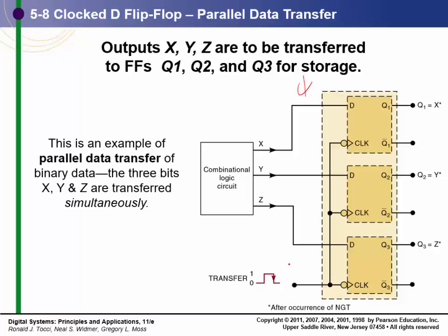You want to latch that music. That's the output of the A to D. And you want to latch all 24 bits of your music, if it's CD quality sound, at the same time, and you want to get it at exactly that time. You would use this type of latch to grab that data so that you know you get it when you want it.